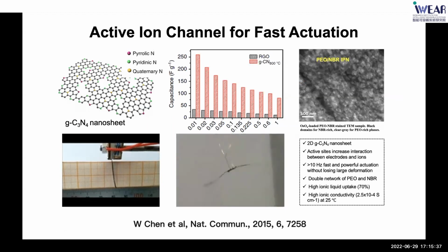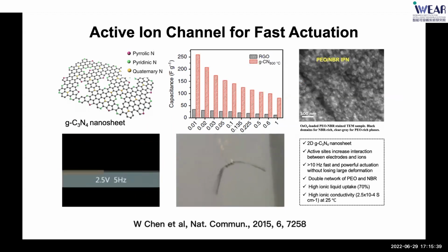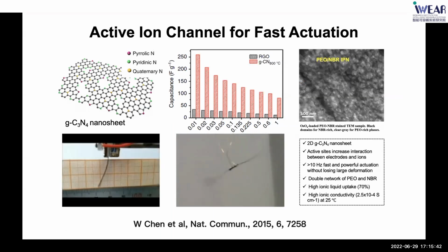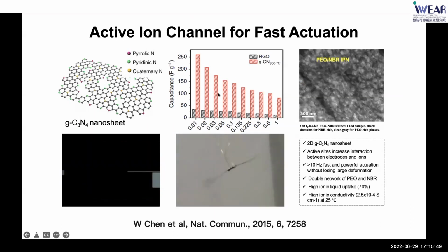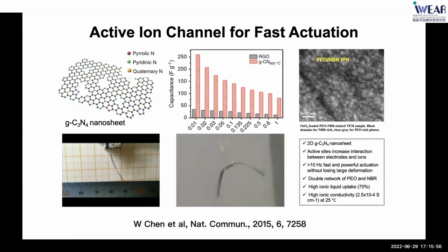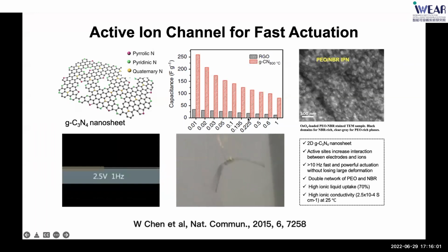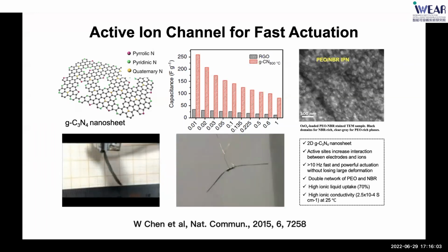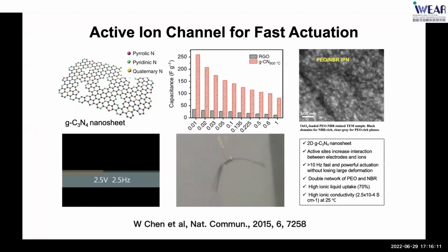Our idea is to use the active sites to increase the interaction between the electrodes and the ions. The direct evidence is shown here. You can see the capacitance was increased significantly due to introducing the active sites. Then we can achieve very fast and powerful actuation without losing the large deformations.